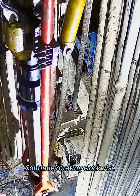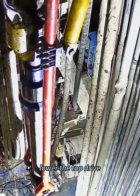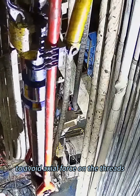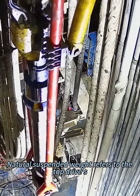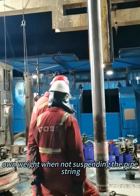Continue rotating clockwise to begin threading the casing connections. Simultaneously lower the top drive, maintaining natural suspended weight to avoid axial force on the threads. Monitor the top drive torque until the required casing torque is reached. Natural suspended weight refers to the top drive's own weight when not suspending the pipe string.